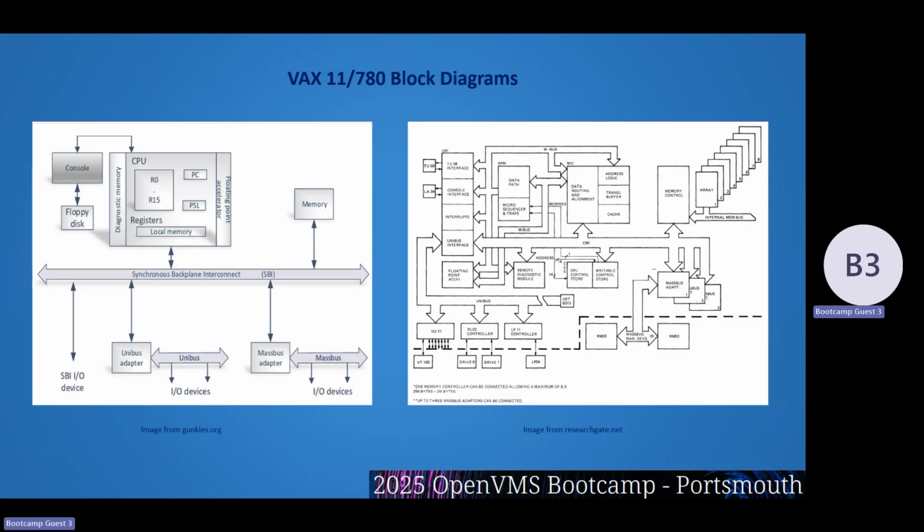This is a memory board and a memory controller from a PDP 1124. So you could have, I think, 3 BA11 boxes in the Unibus cabinet, and the BA11 can have 2 20-slot and 1 4-slot backplanes. I did have one of those, but I couldn't find it. So you could have like 60 Unibus peripherals connected to this.